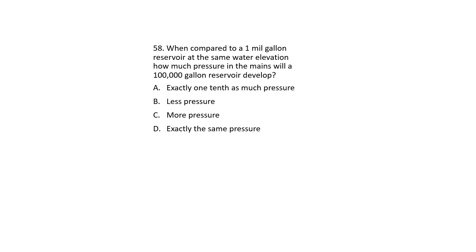When compared to a 1 million gallon reservoir at the same water elevation, how much pressure in the mains will a 100,000 gallon reservoir develop? Exactly 1/10 as much pressure, less pressure, more pressure, or exactly the same pressure? It's going to be exactly the same pressure. The key word is that it's at the same elevation. Foot head would not change.